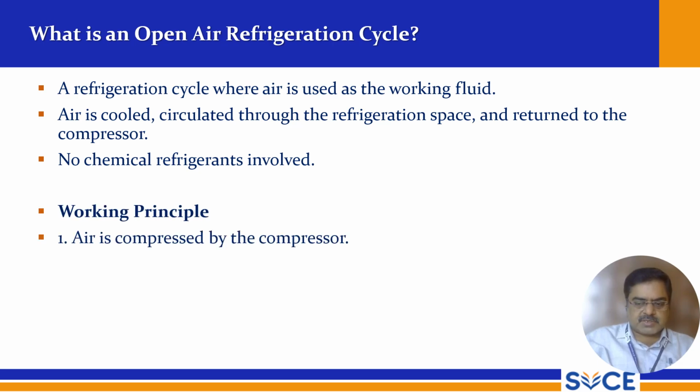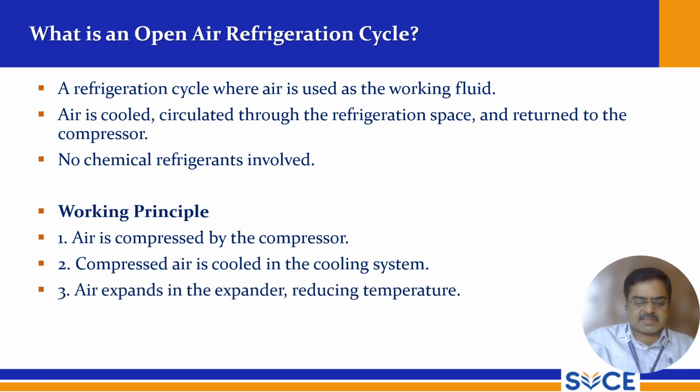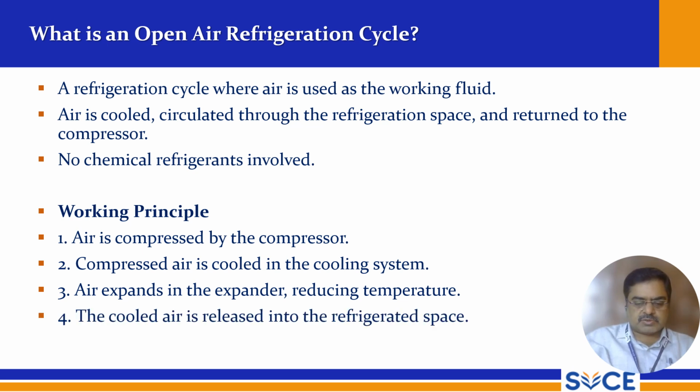The working principle is very simple. Air is compressed by the compressor. So this is the first stage. Compressed air is cooled in the cooling system. So the cooling system cools the air, and air expands in the expander, reducing temperature. Wherever we have a compression process, there will be a temperature increase in whatever medium we are compressing. So that should be cooled and then circulated here.